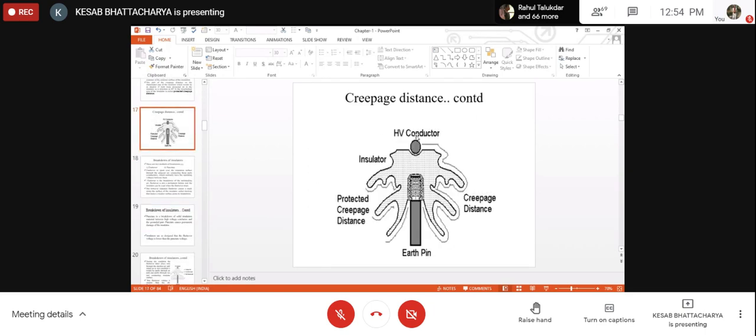here, in the case of flashover, it is ionization of the air outside the surface of the insulator. But in the case of puncture, it is the failure of the insulating material through the body of the insulator and between the two conductors which are at operating voltage. So, if puncture occurs, there will be a short circuit between the two conductors through the body of the insulating material.